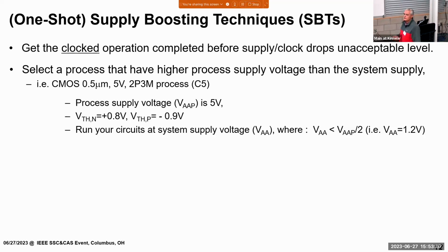And why choose an old technology like 0.5 micron, compared with using a 22 nanometer process or 90 nanometer process? It is the leakage. Low leakage. Again, you have to be mindful about your leakage, right? And all analog processes and most of the power management ICs that you are buying are very old processes. They are not like 22 nanometer or 90 nanometer processes, okay?